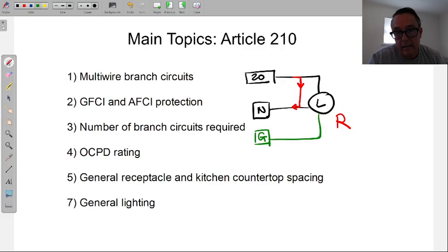This is not a circuit, that's why they don't call it a short circuit. If the hot and the ground, let me use yellow, sometimes it's a little bit hard to see yellow, let me know if it's hard to see, but if the hot and the ground come into contact, this is a ground fault. All right, so just two terms. You don't have to write those down.